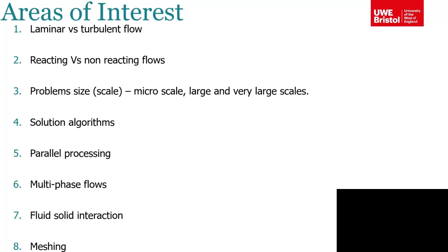So for example, if you have combustion inside, you have fuel and oxygen and nitrogen, and then CO, CO2, H2O, H2, NO, NOx. So you can have multiple species, that means you have to solve an equation for each of these species. So your problem becomes much larger when you have reaction.